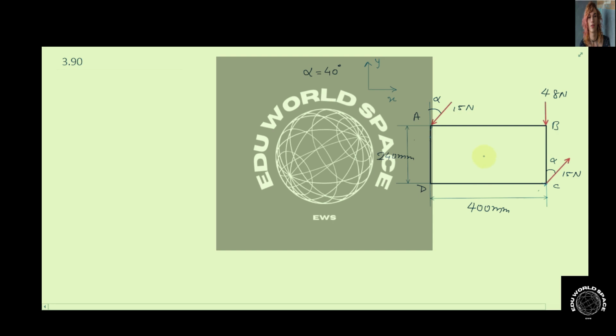So the only effective force acting on this system for the calculation of the equivalent force will be 48 Newton. I am considering this axis to be the x-axis and this axis to be the y-axis. So this will be minus j prime. So the equivalent force is minus 48 Newton j prime.